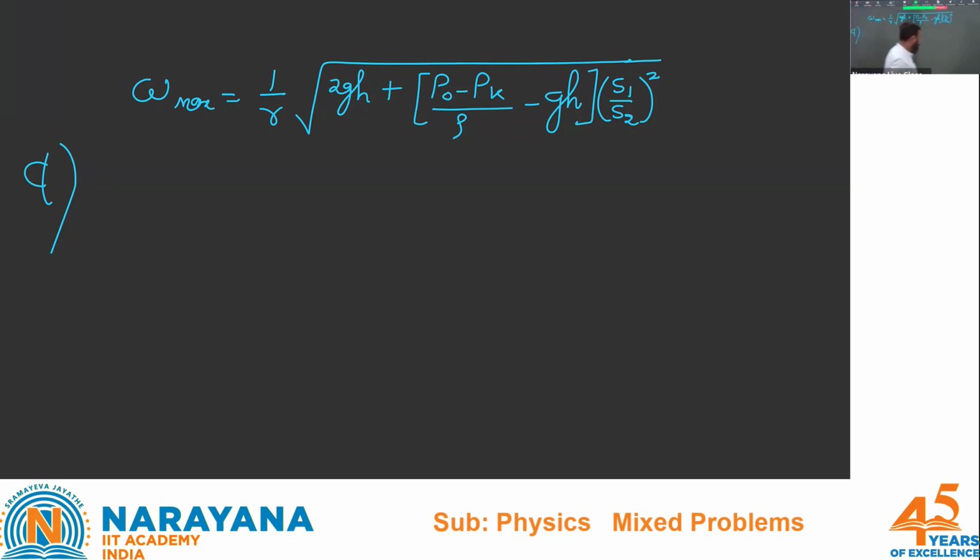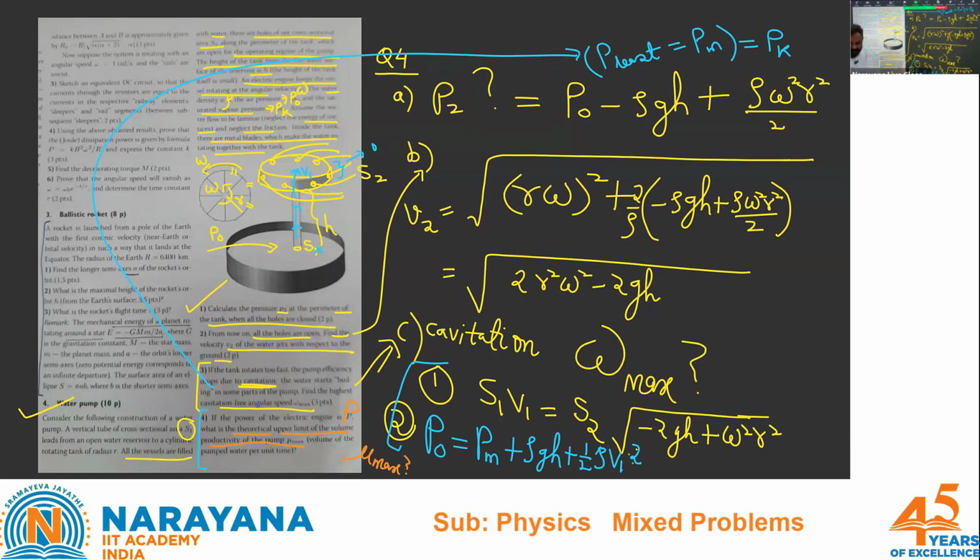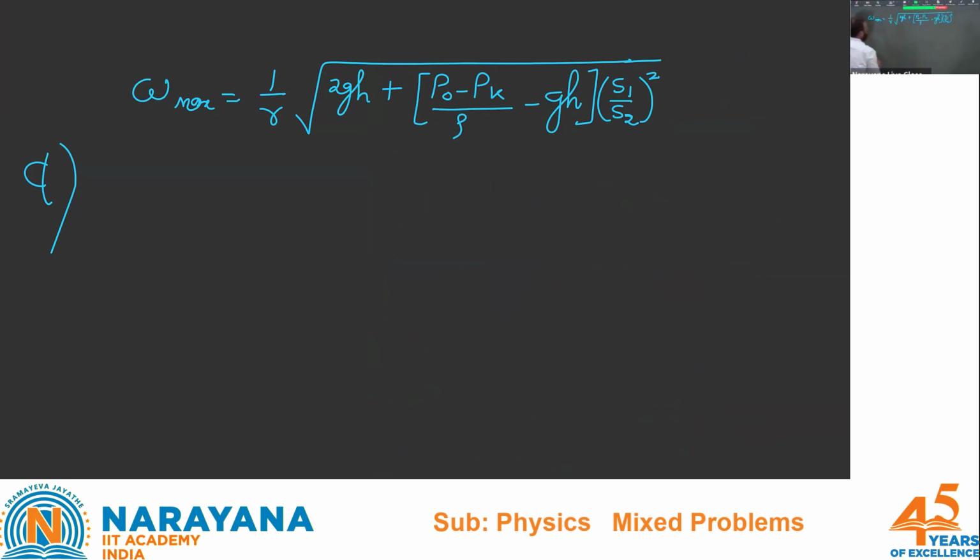And one more thing, I also have to ensure the cavitation issue that is also there. The thing is, if you look into your expression of omega max, there is again a limit to that expression. Let's see what the expression is. Before you can solve for D part, you need to see your expression here, and you need to see that the limit that you can provide for this value is 1 upon R into root 2GH. That term can have a value of 0 also.